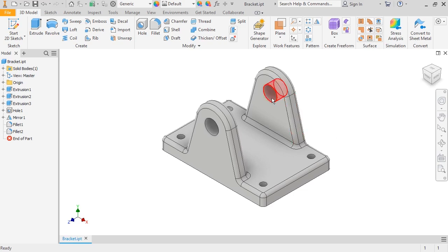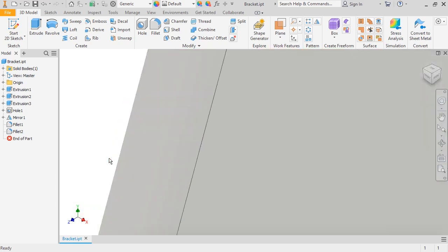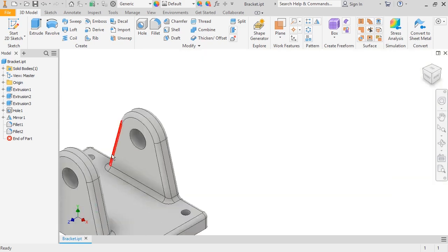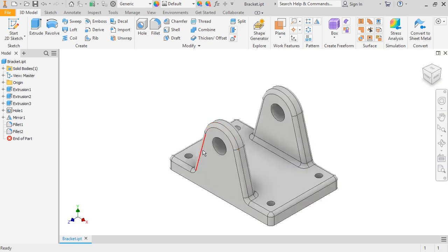So, to recap, you can pan by holding the middle mouse button down. You can zoom in by rolling the scroll wheel towards yourself while adjusting the cursor every few seconds to zoom into that area, and zoom out by rolling the middle mouse wheel away from you. If you zoom out too far, just double-click the middle mouse button for Zoom All.